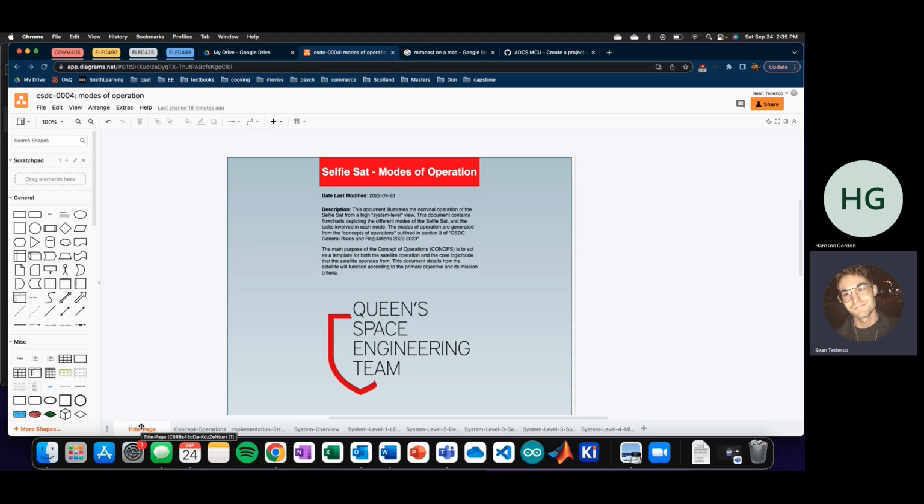I know you talked a bit about the surviving, so I didn't see a graphic for it, but for example, there were two faults. One was a sun soak to be able to drop it. So if we have, for example, a low battery, we have an over temperature. Is there an order in which they'll be processed, or if we're dealing with one fault and somehow another comes in? Yeah, we were just thinking about that. I think every fault will have a priority at a minimum, like a description, priority, and maybe frequency of occurrence.